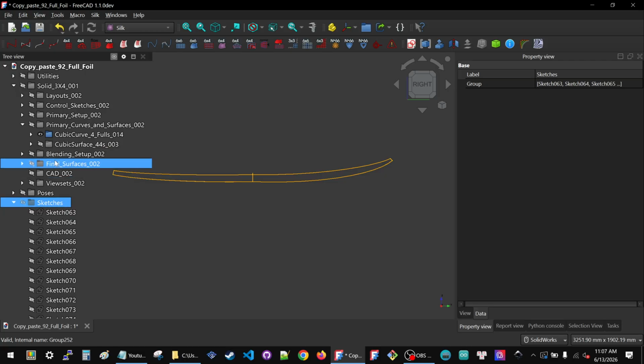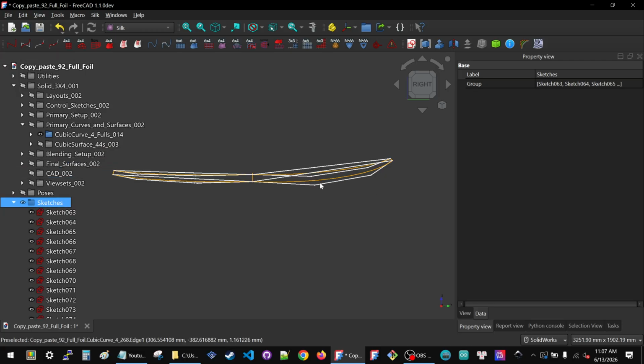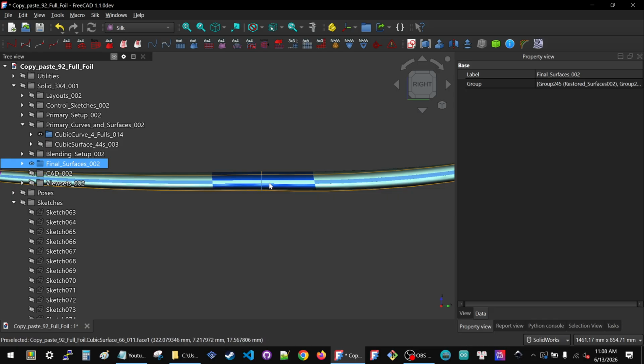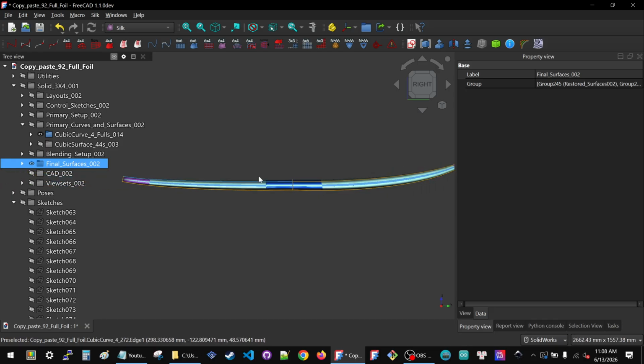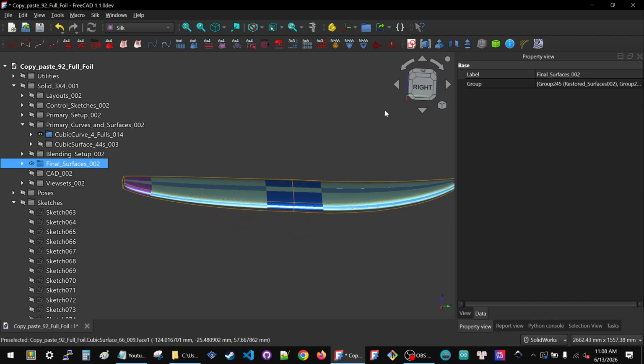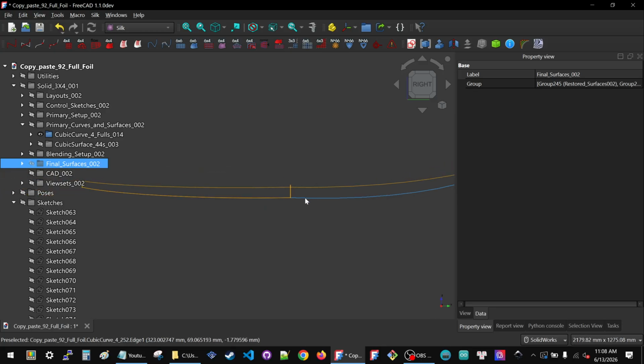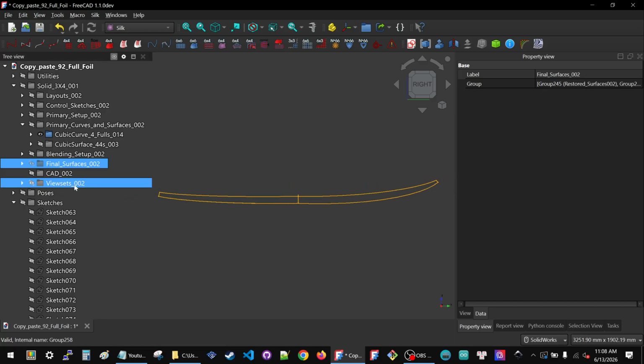As a matter of fact, let's see what the effect of what we did just now is. See, now there's a little bit of a bounce right here. The blend is there, but it's bending, and that's because I've allowed this line to go down too far, because I moved the curves, I dragged everything back to the left, and so this point that was here has just gotten shifted here, and now it's pulling down too hard on this portion. I definitely don't want this curve to be going below horizontal. So let's fix that.